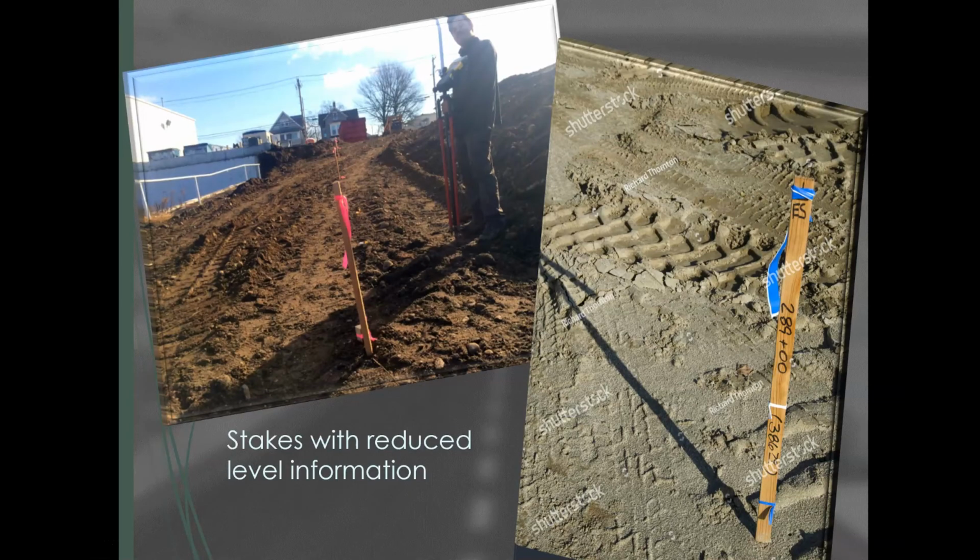So when we set out a vertical curve, what we are required to do is put some kind of stakes or pegs or pieces of wood, and put some information on that particular stake, in this case chainages and some kind of reduced level.